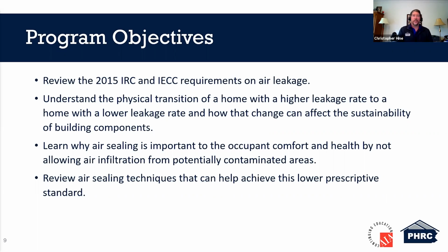So for instance, if we have a home in the wintertime that has a high relative humidity and we have leaky can lights, that's exfiltrating from the conditioned area into the unconditioned attic, but it's contaminated with moisture, and then you have an issue of condensation or potential condensation. So it's not necessarily just contaminated exterior air that's carrying with it mold and pollen and things like that coming in, but it's also what we'll call contaminated conditioned air exfiltrating into areas that can, again, potentially cause issues.